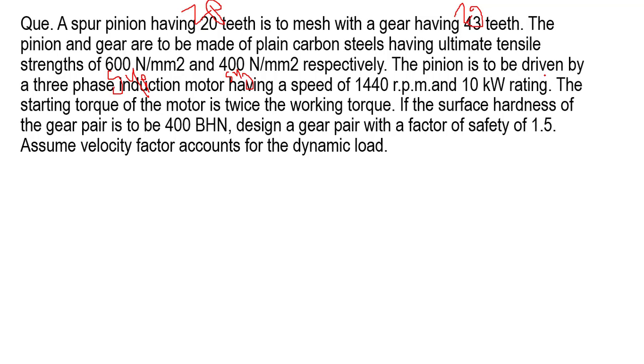The pinion is to be driven by a three-phase induction motor having a speed of 1440 rpm. Generally for an induction AC motor the speed is 1440 rpm, and rating is 10 kilowatt. We will use watt, so it is 10,000 watt. The starting torque of the motor is twice the working torque.